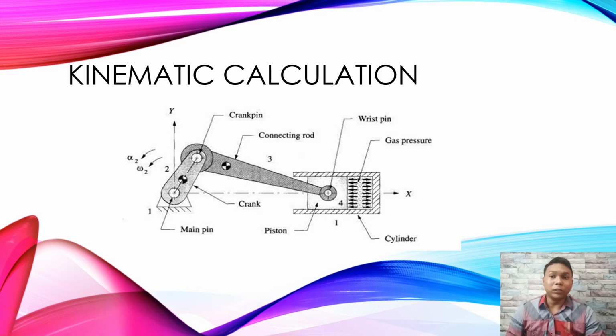The fuel is burned in the combustion chamber during the combustion process. The piston is pushed along the negative x-axis by the combustion process, which boosts the gas temperature and pressure. The crank slider mechanism comprises a wrist pin, connecting rod, crank pin, crank, and main pin, converting linear action into rotating motion. The torque generated by the crank rotation is used to propel the car or other equipment.